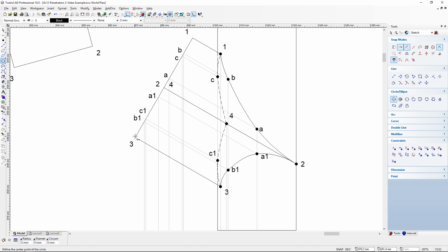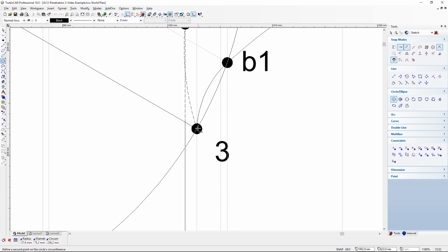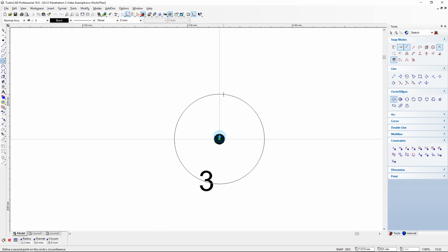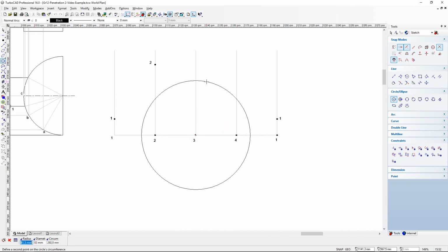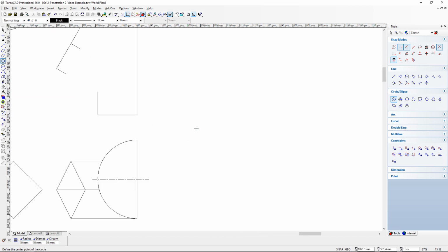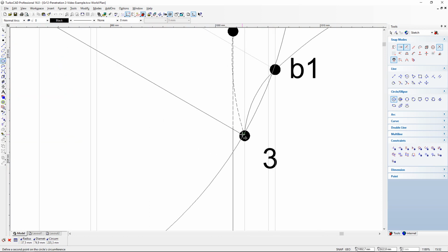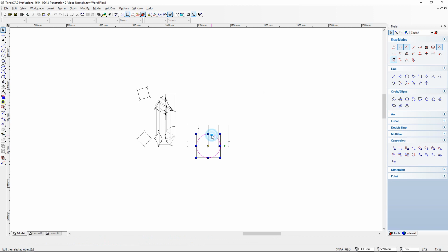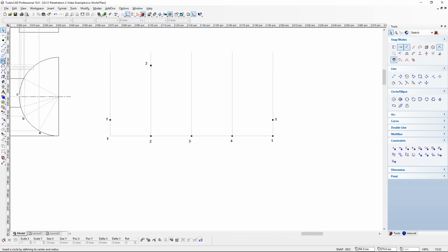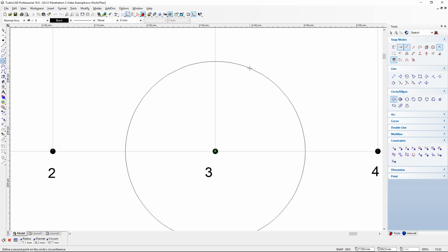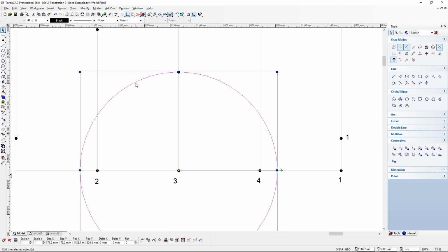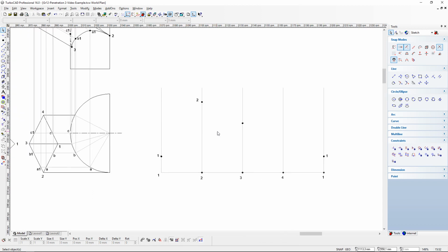So I'm going to go to number 3. The height is 37.6. I'll move to number 3 segments. Tab 37.6. Just double check that height. 37.6, pardon. So let's just fix that. 37.6, sorry. Tab 37.6, and then we plot that dot. It's very important to double check your measurements, because if you make a mistake here, obviously your development will be completely wrong.